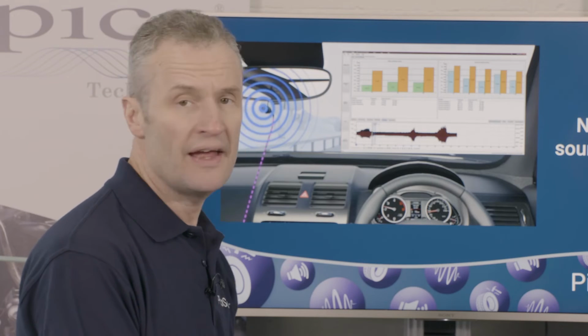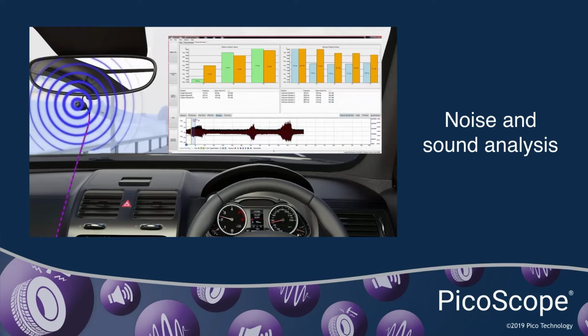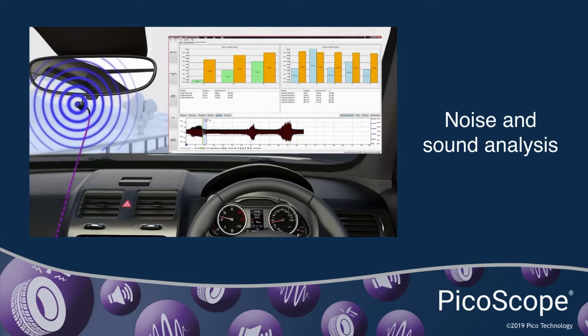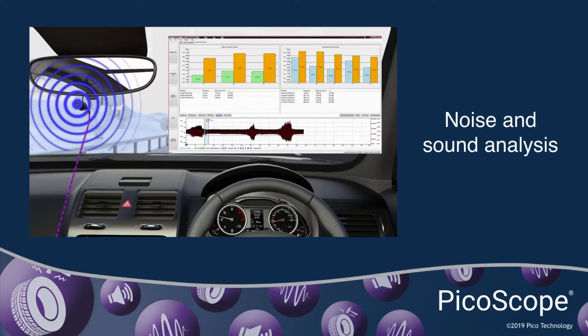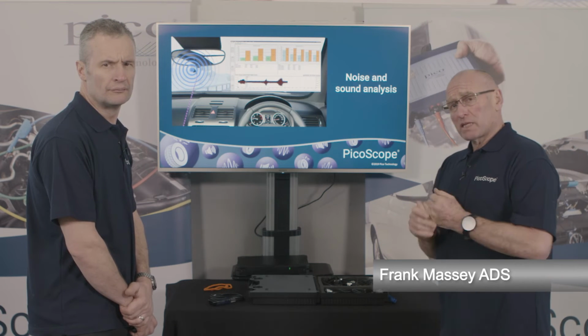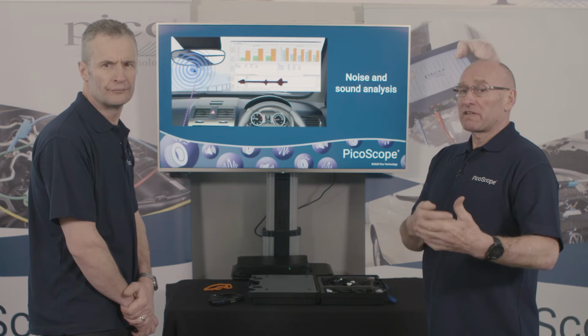On the right hand side you'll see the top 5 unknown vibrations, and that's unknown because it's not linked to engine or road speed. It's an electric cooling fan. So what I've picked up there from the bar graph, Steve, is that it is an unknown frequency. It's not related to anything that we're able to synchronise from known data from the vehicle setup.